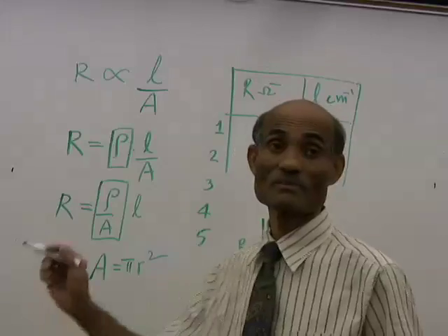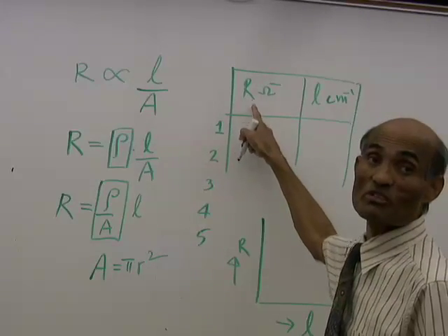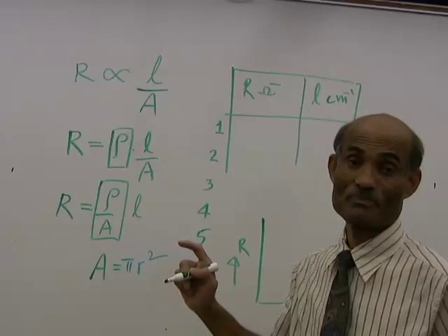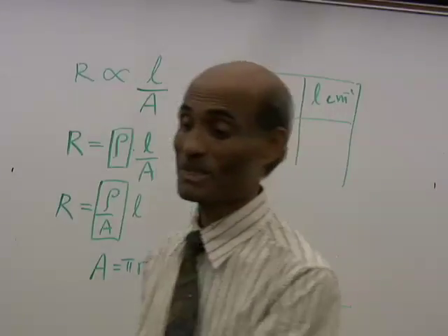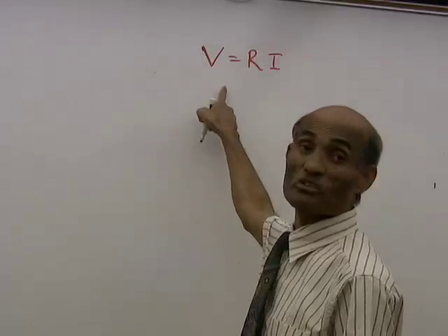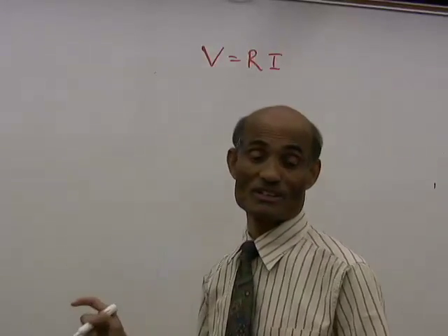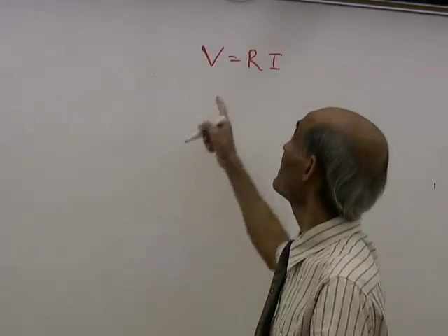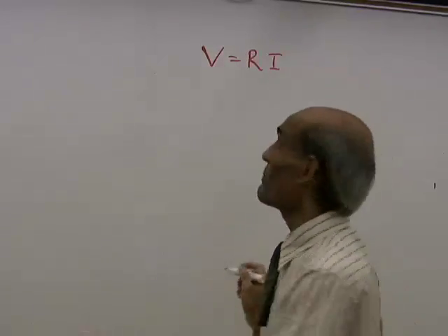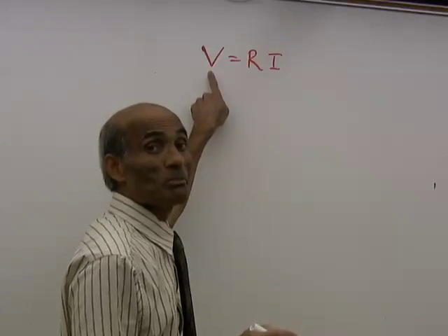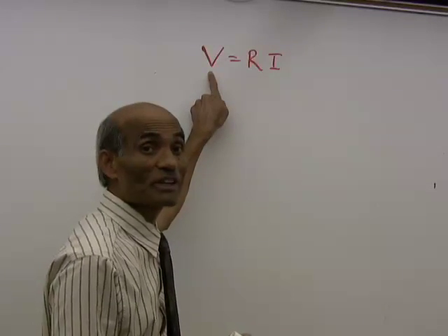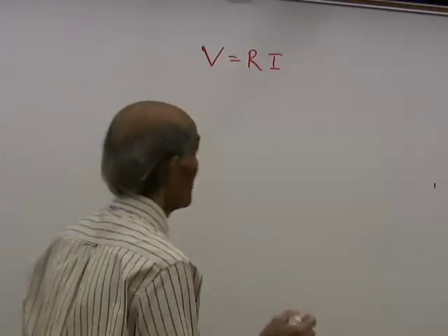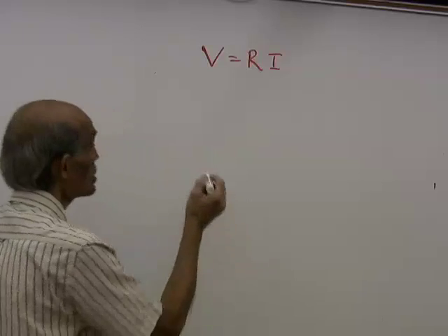What is the first part? Measure the resistance of 5 samples of nichrome wire. And that is our first part of the experiment. Now, this is the Ohm's law equation that we will be using to work with in this part. V equal to Ri. That means we need to measure the potential difference across a conductor and the current I that flows in it. Alright, let's first of all set up the circuit.